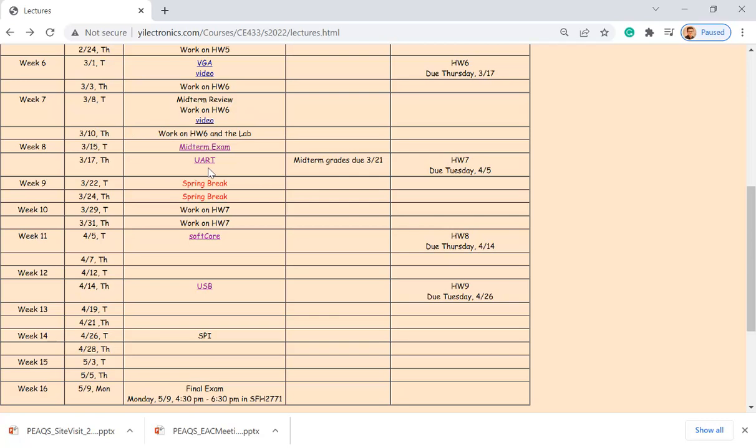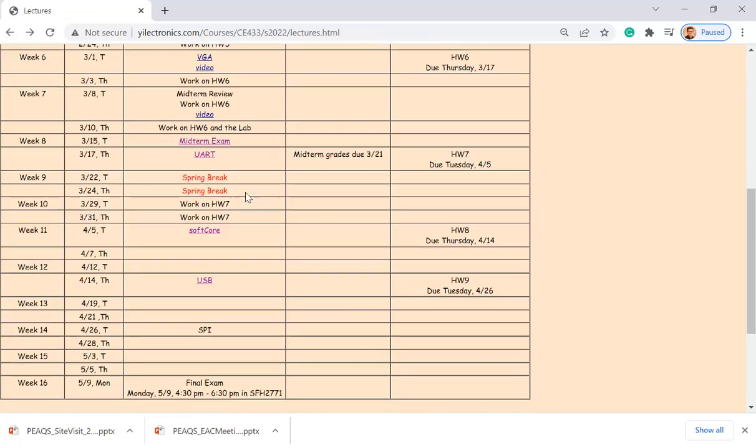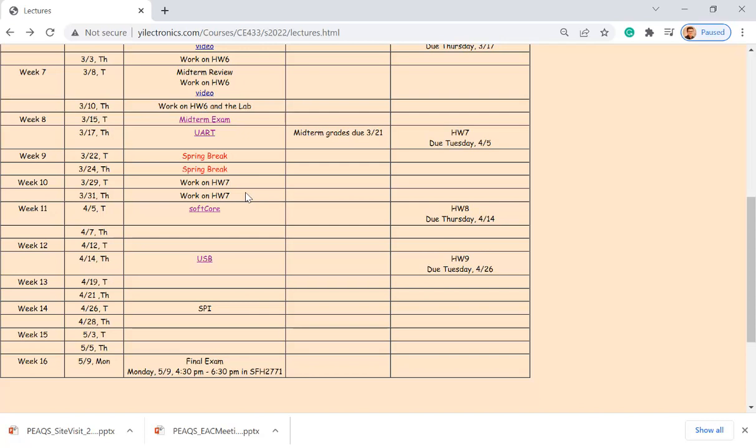Whenever you are downloading an Arduino script onto your Arduino board, it's actually communicating through TX and RX, which is UART. It's a universal asynchronous receiver and transmitter. Whenever people talk about serial, it's usually referring to UART if they're not specifying some other serial protocols. If they just say serial, it's usually just UART. Okay, it's the most commonly used digital communication protocol.